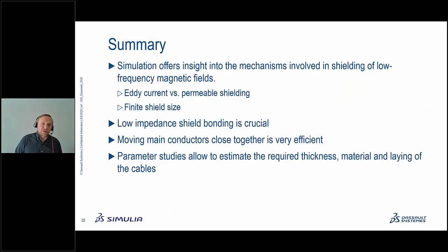So summarizing the part about the cables, I think you can use the simulation to gain insight into what's actually happening, to see the different shielding effects of the eddy current shielding and the permeable shielding, and also to see, I mean, this is something that you can read in a book, but once you come to finite sizes, like the finite shield size, when I have moved the shield away from the distance, that's something that you will typically not find that much in a book, because simply the expressions or the analytic solutions to these models become complex.